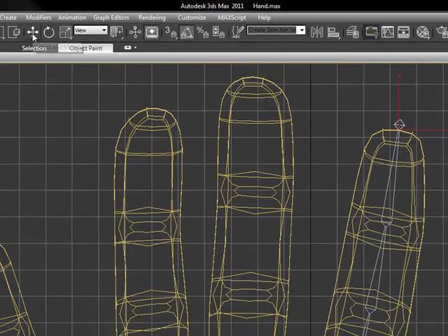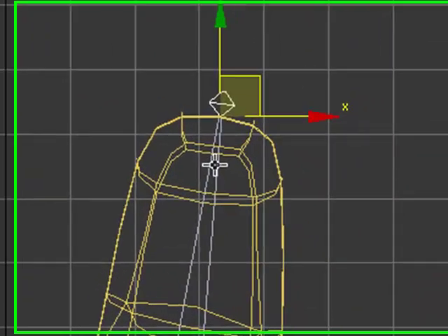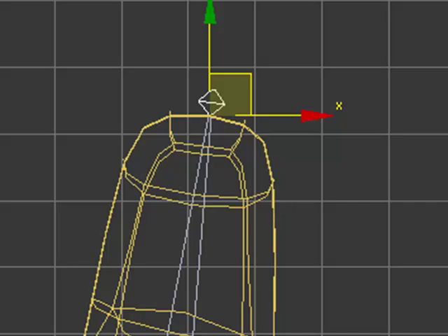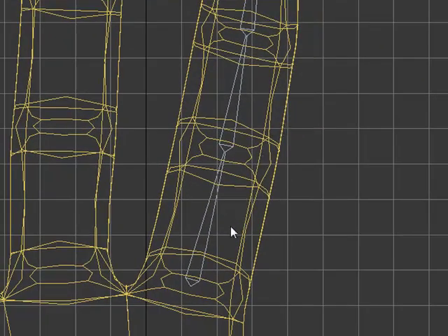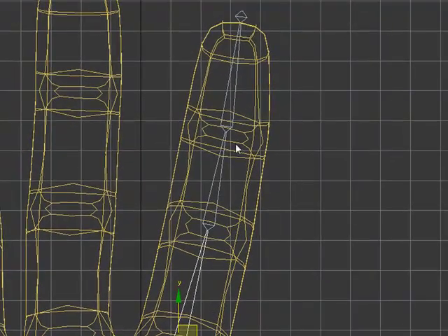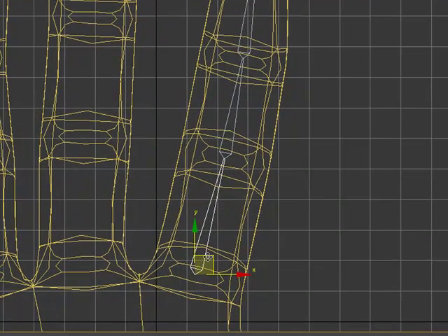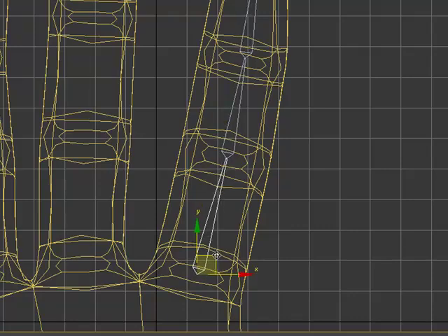Now you're going to get this little diamond on the end, and that's fine. That's going to be used as a controller, which will allow us to use inverse kinematics to adjust our finger. But when you line up your bones, one, make sure each joint is lined up at the knuckle, but two, the bone is somewhat centered in the hand. Now using kinematics and the link, the bone system automatically has the link involved. So by moving the parent, you'll notice that the other two bones follow.